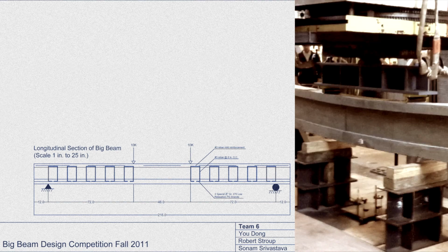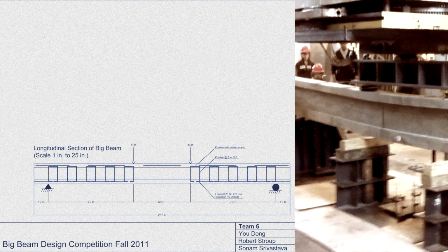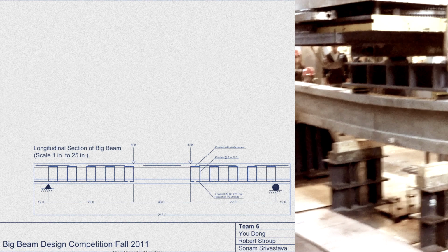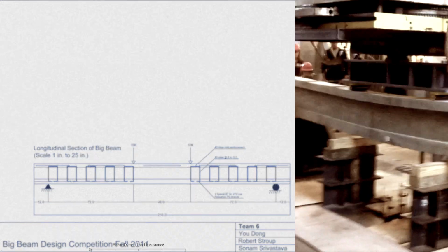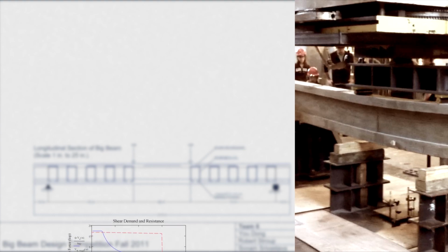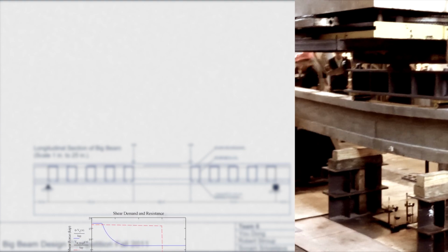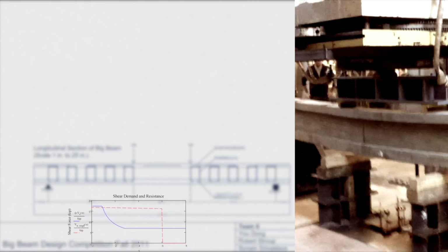Using the depth of the equivalent compression block, and then using strain compatibility, a new pre-stressing force of 266.62 KSI was then found. Using this newer value of force, one more reiteration showed the pre-stressing force to be approximately 3 KSI less than the second iteration, and a third and final reiteration verified this to be true, given that the change from reiteration 2 to reiteration 3 was minimal.